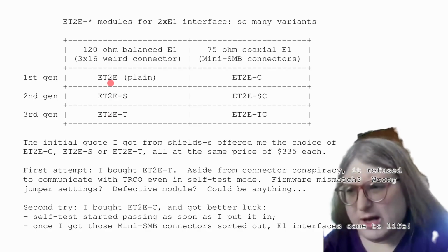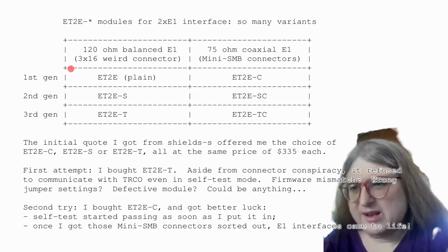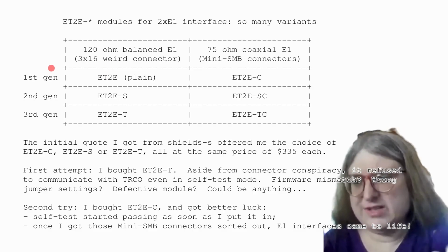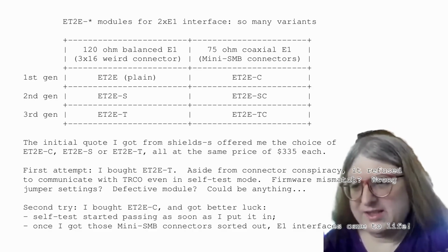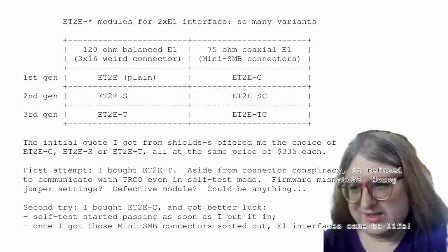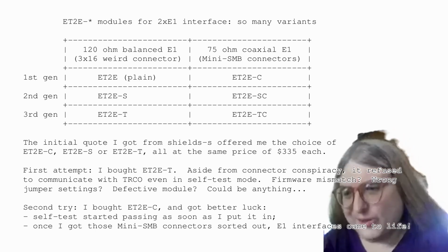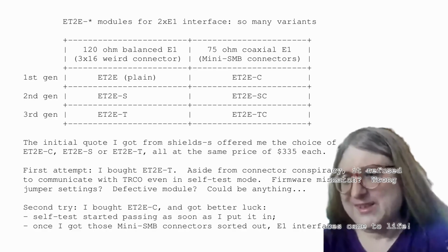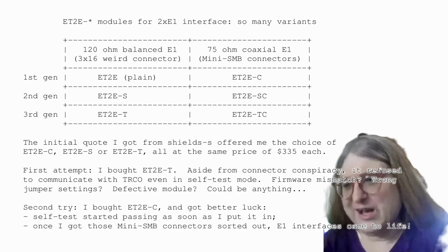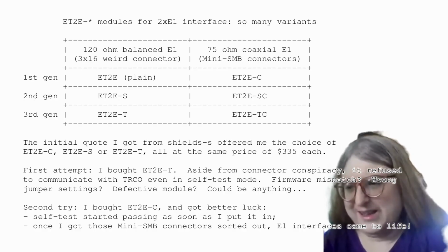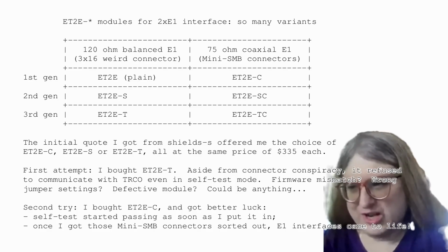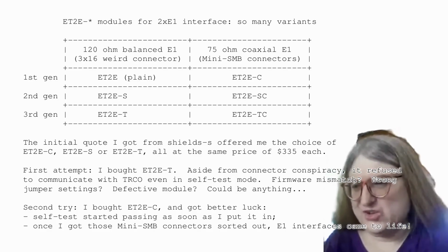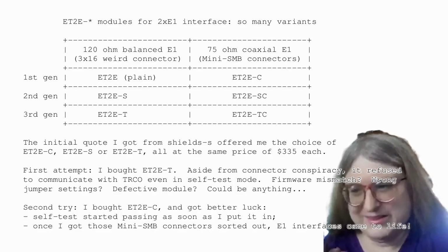So they all have a connector that's basically half of that standard DIN 41612. So it's a half C size. So the 3x32, it's 3x16. And it also has those weird tabs. So even there, the standard plug would not fit. And there's no way of removing that shell at all. That one, the exchange terminal module, there's the metal bracket and everything.